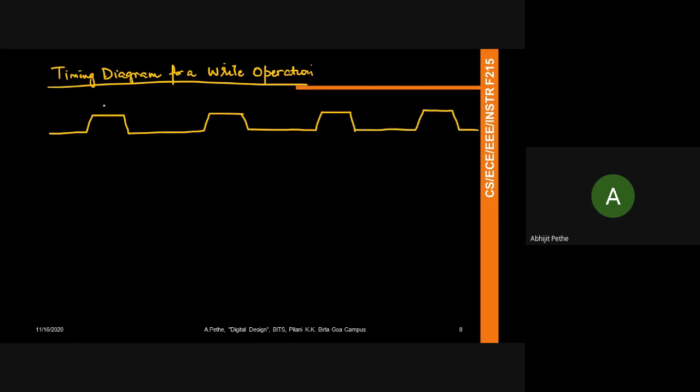And let's just number these clock pulses. Say I'm sure I can write any word into this memory within 3 clock cycles. I've budgeted a write operation will take only 3 clock cycles, right?